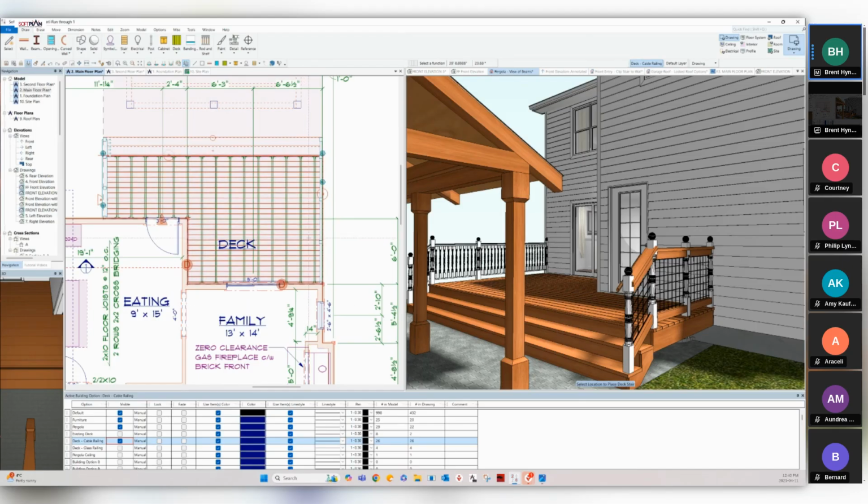So that's multiple building options. Depends on what kind of drawing you do, but building options are something that just about everybody can utilize in some way. Typically used for houses that you've drawn and use multiple times, but you have different options for them. Use your building options to set up that breakfast nook, that peninsula in the kitchen, that kind of thing. Different windows on the front facade, different roof pitches, that kind of thing can all be utilized through building options, and having the multiple options is very useful in achieving that.